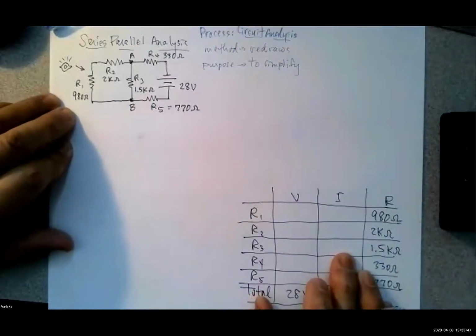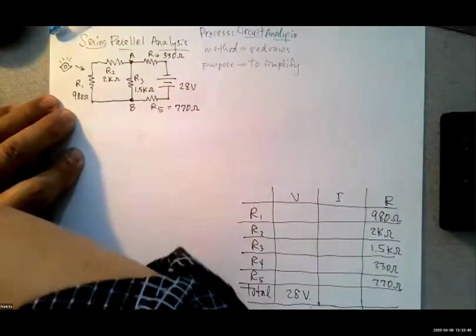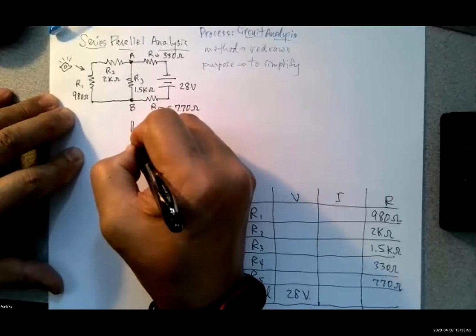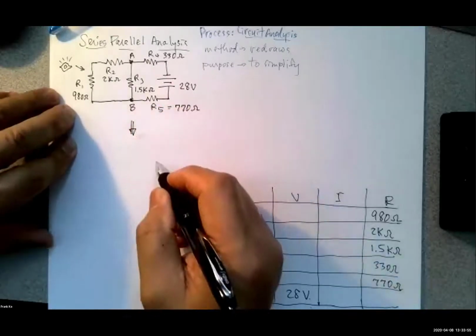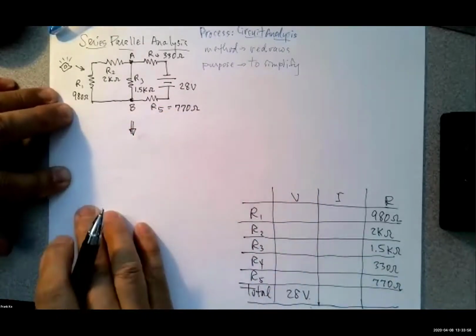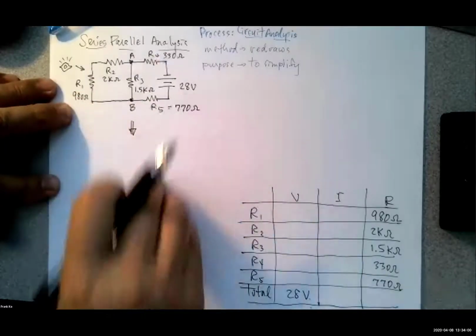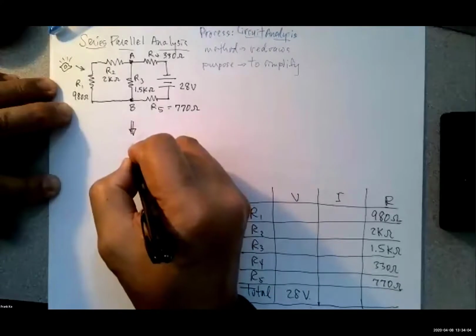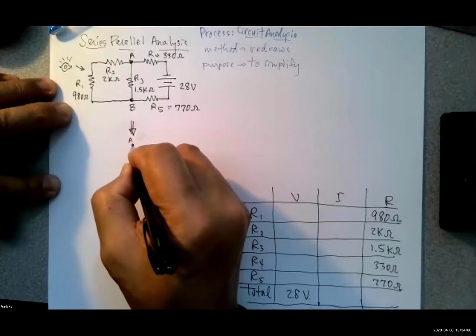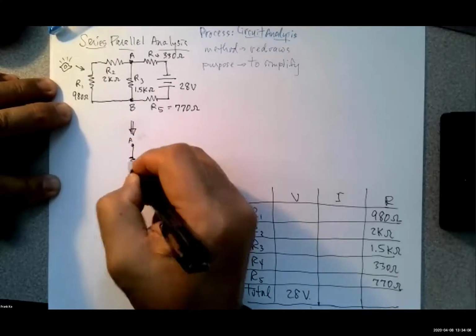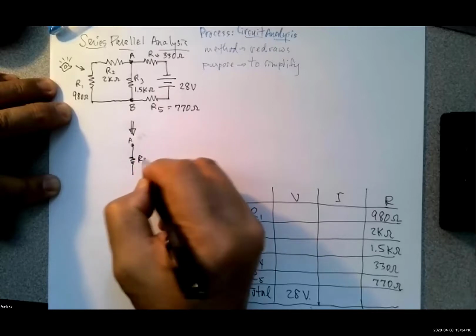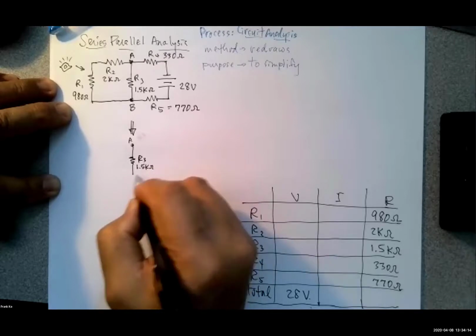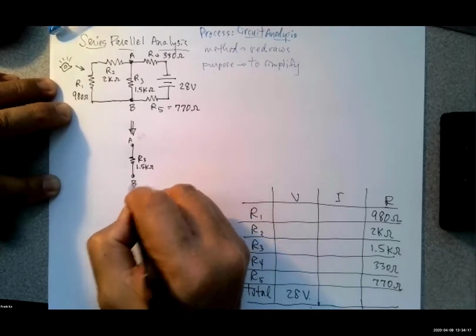Circuit analysis. Cool. All right. So now we're going to redo this particular guy. And in the redraw, my recommendations are always to save some space below your original schematic and draw directly underneath your original schematic. And so I will retain point A. I will retain the original R3 at 1.5 K ohms. I will retain the original point B.